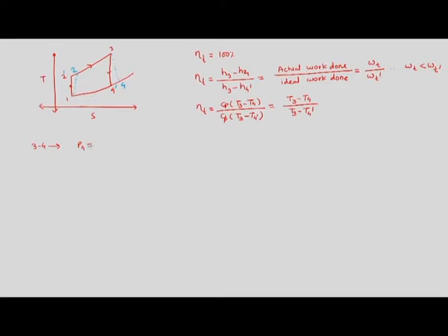We know that P4 is equal to P4 dash, but for finding out the temperature T4, we know the turbine efficiency, we know the pressure ratio, we know T3, which is T max by some means, and then we know gamma. So these are things which are known to us. So now what we can find out is the turbine efficiency, which is equal to (T3 minus T4) divided by (T3 minus T4 dash).